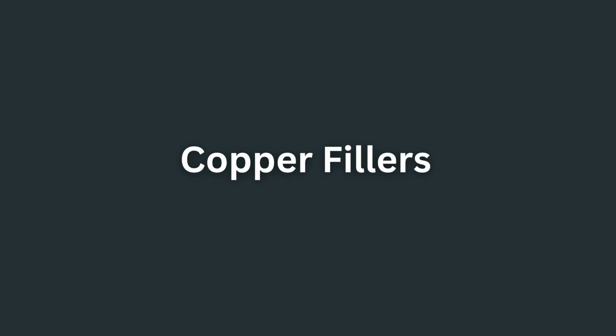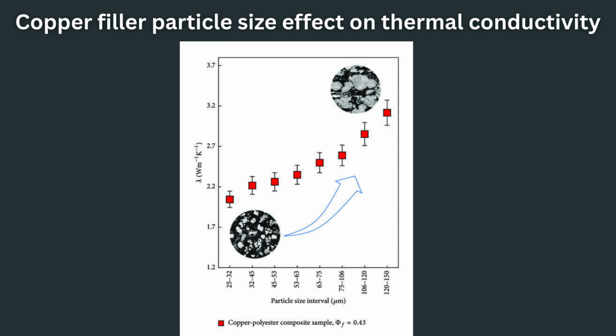Copper fillers. Copper is widely used for its high thermal conductivity and relatively low cost compared with noble metals. The thermal performance of copper-filled adhesives depends strongly on particle size, morphology, and loading fraction. Studies have shown that copper powders with particle sizes of 50 micrometers, 75 micrometers, and 100 micrometers can enhance thermal conductivity when incorporated into polymer matrices.